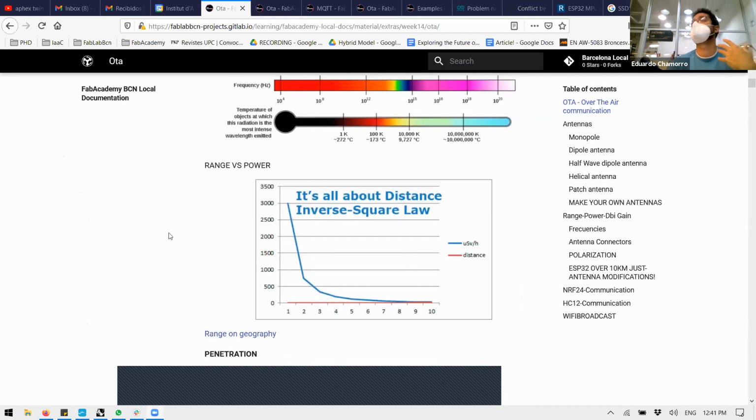About power and frequency transmission, this is the inverse square law. You can double the power but not even get a third of the increase in range. How do you actually get longer distances? Either you increase the gain and sensitivity of your receiving antennas, or you change frequencies. There is no other science behind it.